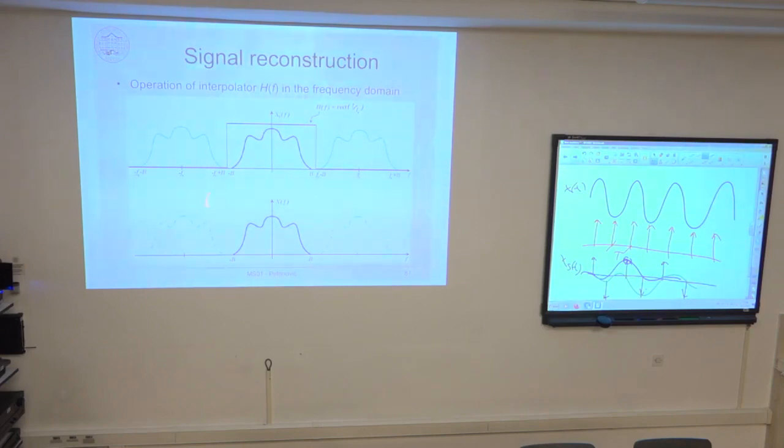But most of the filtering is done in the oversampled digital domain, where this oversampling factor is maybe 128 times or 256 times to achieve almost ideal operation as the sinc filter described here. Okay? And it is an integral part of your audio codec that is integrated either in your phone or on your sound card in your computer, or this codec that is on the motherboard. So all of these audio range AD converters are based on this oversampled sigma delta architecture.